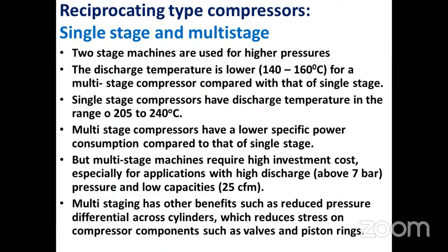Multi-staging has another benefit also, sir. Because the pressure is divided into two stages, the pressure across the cylinder is low, and it results in lower stress on the compressor, and wear and tear will also come down.